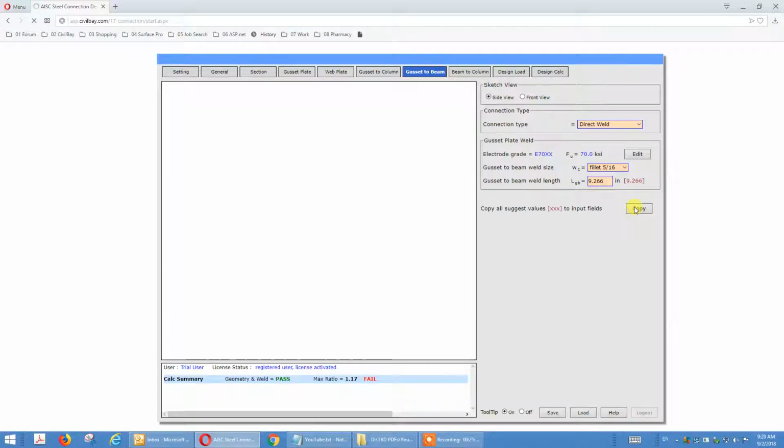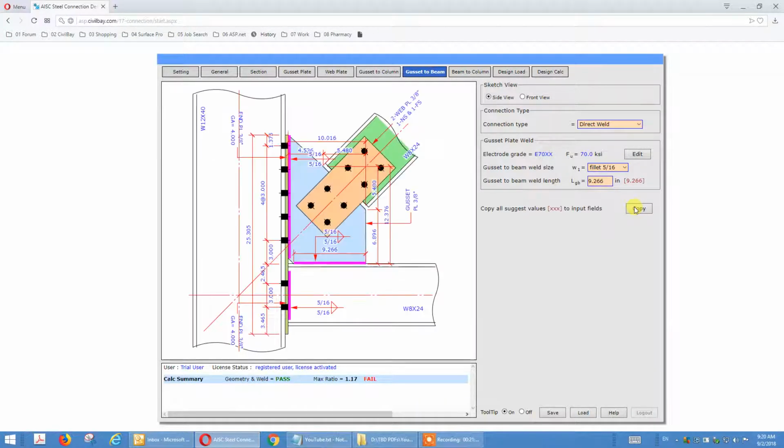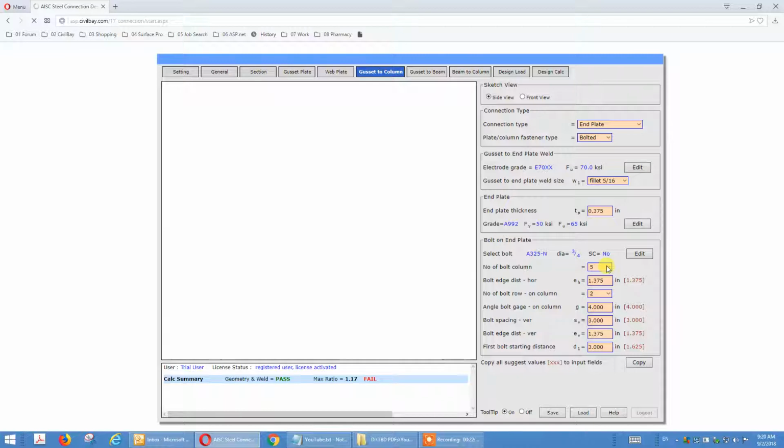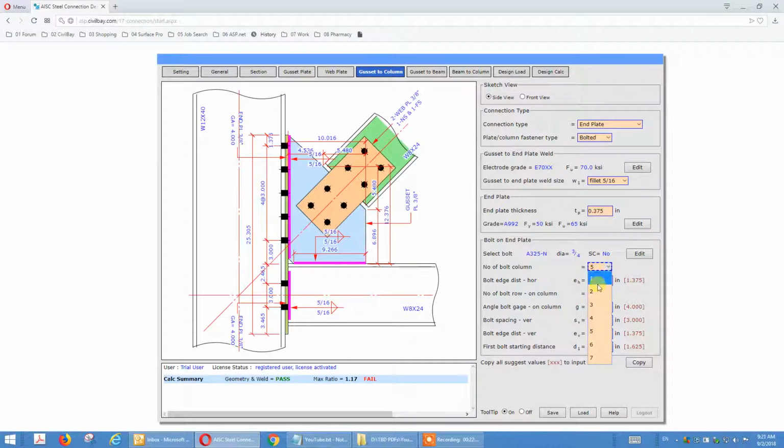Keep adjusting the number, the gusset geometry too, because different way of connecting, different way of gusset to column. I will just reduce it, now it's 5. Different connecting approach has different footprint on the gusset size. So I go to 3.